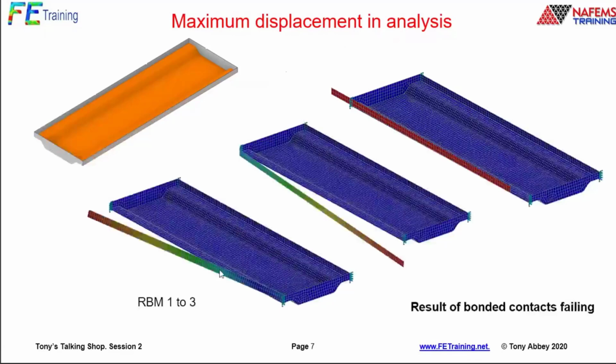So here's an example. This was a structure I ran, and I had issues with the CAD model. I had used a contact surface in this particular case to connect these different strips together, due to the fact that mid-surfacing and offsetting and so on coming through from the solid geometry was difficult. It was easier, I thought, to just bond everything together. Now I set the tolerances wrong in the bonding, so a couple of things happened. First off, it wouldn't run in a linear static analysis. I'll talk more about this at the end.